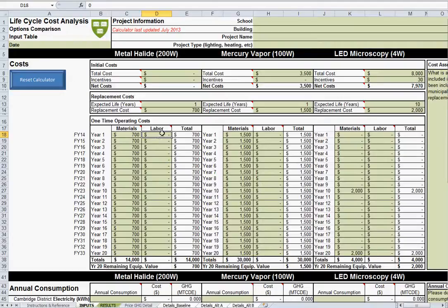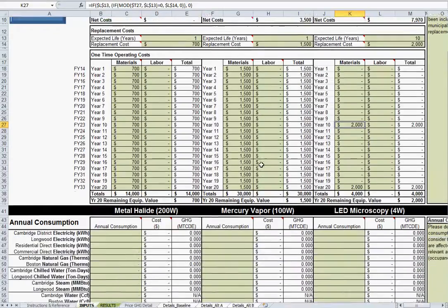If we're looking at large-scale fluorescent lighting, lamp replacement can be very big. You could have a facility with thousands of lamps in it, and even at 5 minutes per lamp, that adds up to hours and hours of labor that you have to do every time. It's actually one of the big drivers of LED savings, frequently the lamp replacement schedule. This is not uncommon. The scale of the numbers is a little strange, but the general concept of LEDs far outlasting their counterparts is very common, both at the process microscope level and at your typical lighting scale as well.